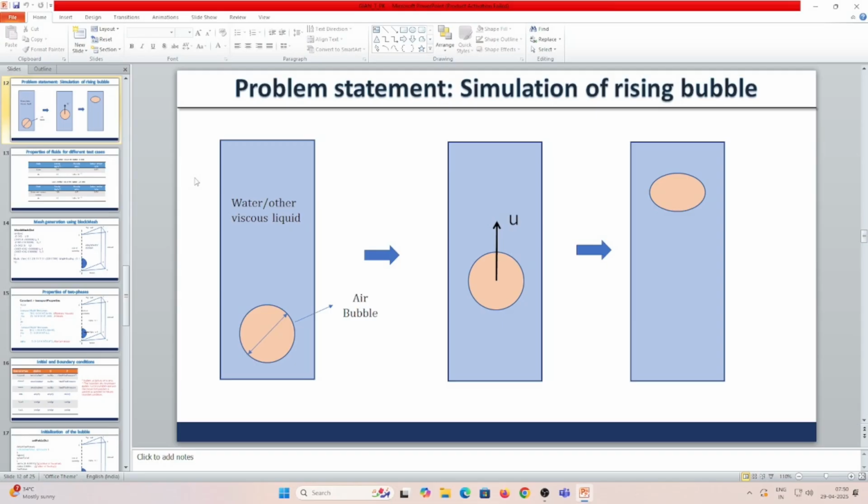So maybe I think all of you are able to run. So with this we have only seen what are the basic ideas of the interFoam solver and how we can set up a simulation in interFoam and how we can run that simulation. If we have to do any new case using this solver, it is always advised that we should select the closest case and then we modify the case files, because writing each and every file from scratch is not an advisable idea. We will be making a lot of mistakes in putting various colons or commas or brackets. So better way is we can take the closest file and we can modify that.